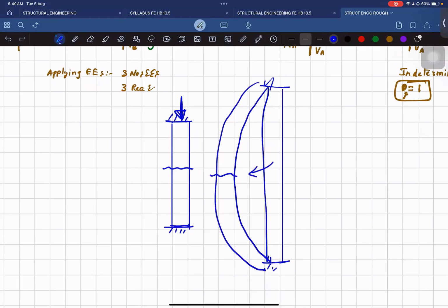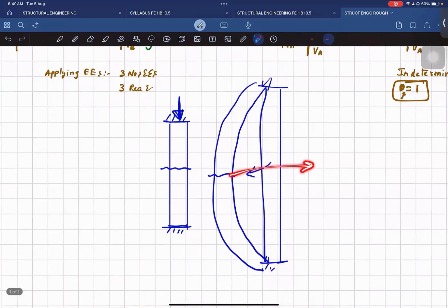It is also a failure because it failed to serve our purpose of carrying the load vertically. It is a structural failure. We call this failure buckling. Crushing is also a failure because it also failed to transfer the load. So whether a column undergoes crushing or buckling depends on something called the dash ratio. What is that ratio? Slenderness.